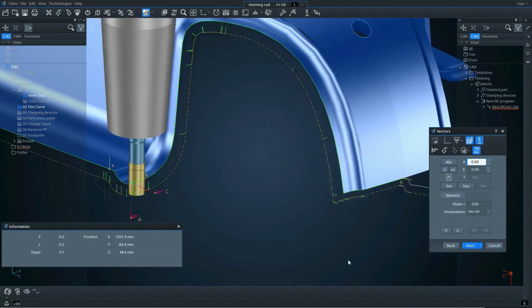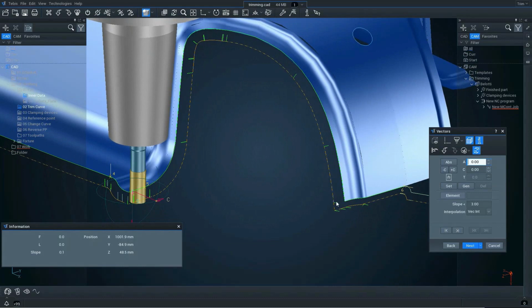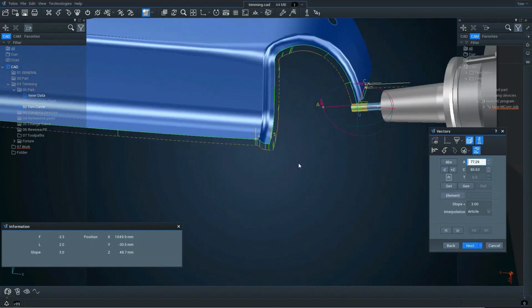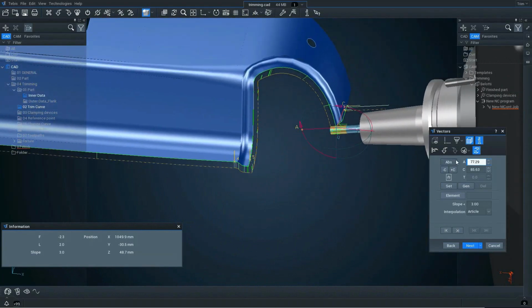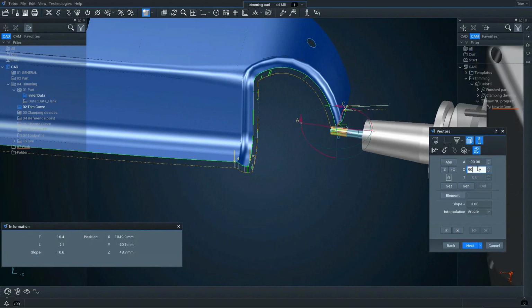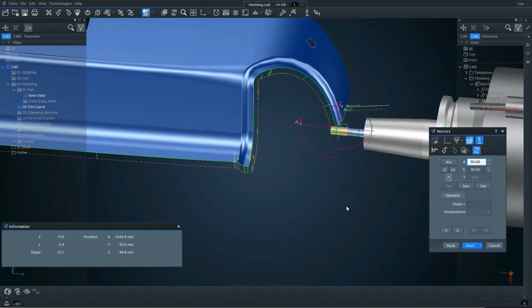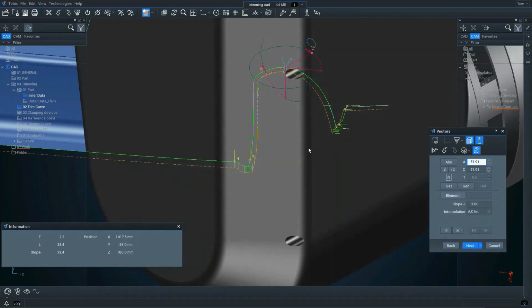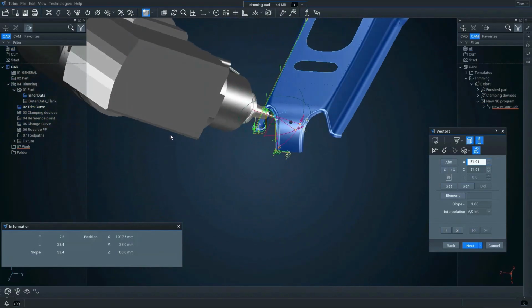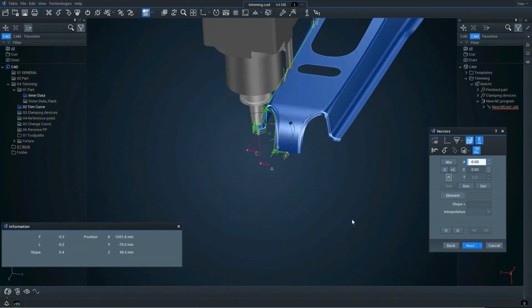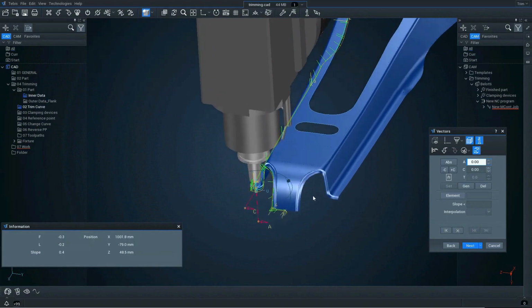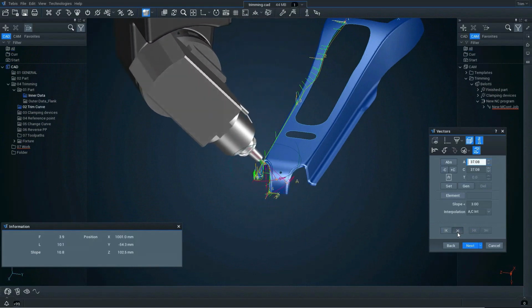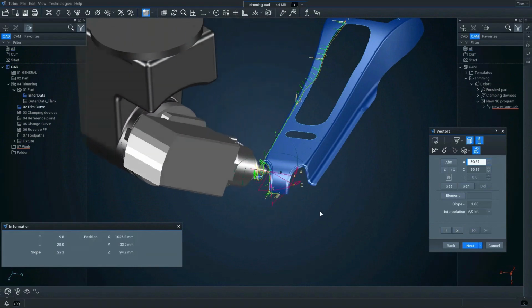Now with this heavily rotational area, what we want to do is allow Tebis to do a little bit more of it itself. So we're going to allow it a little bit more freedom, a little bit more movement, but we're going to nominalize the value at the end. And in between, we're going to tell Tebis to rotationally interpolate. So what this means is when we come from point 5, Tebis will very cleanly and very smoothly roll around that component to create a nice toolpath.